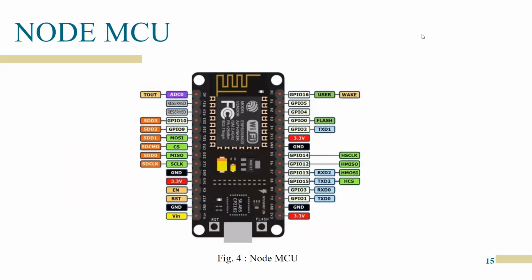Yeah, so let's discuss this Node MCU. The microcontroller we are using here is the Node MCU microcontroller. Actually, this Node MCU is similar to the Arduino microcontroller. It is actually a modified version of the Arduino microcontroller. The code that we use in Node MCU is the same as that we use in Arduino. The specialty is that the Node MCU has an inbuilt ESP8266 Wi-Fi module in it.